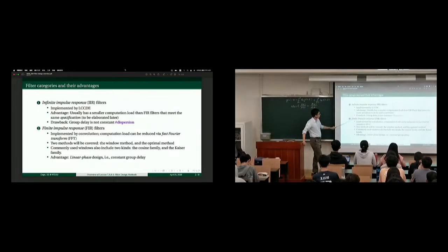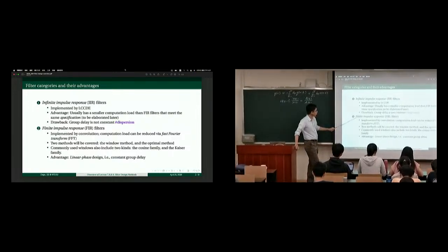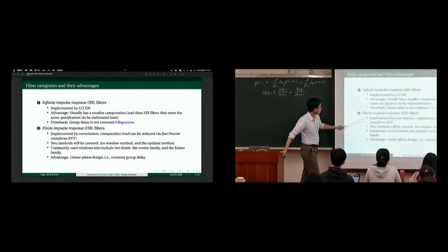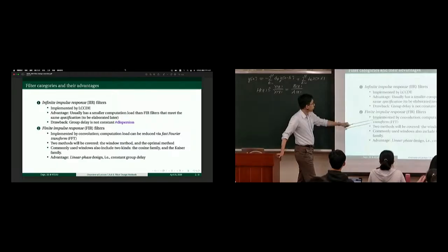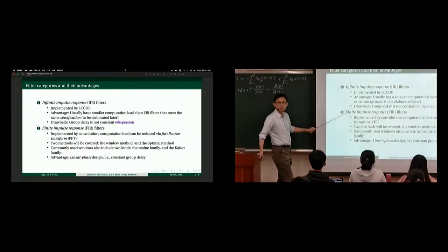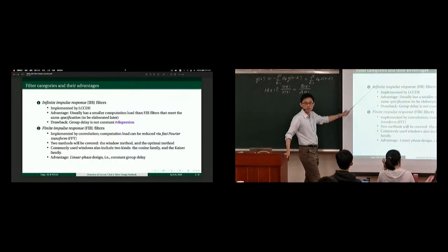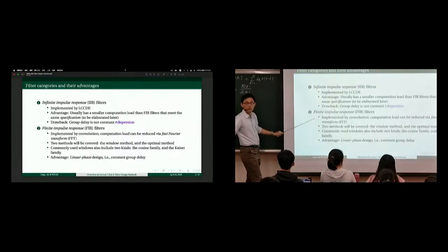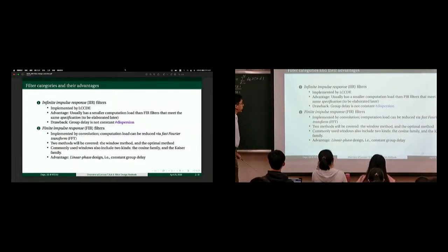Versus the other kind is, of course, infinite versus finite. The second kind is in a sense easier, called FIR: filters with impulse responses that are finite length in time. Finite impulse response, infinite impulse response, FIR and IIR, two different kinds, and their design requires a very different way of thinking.